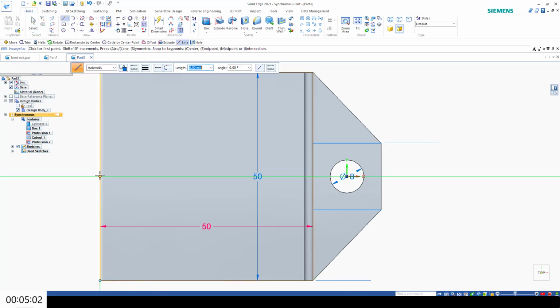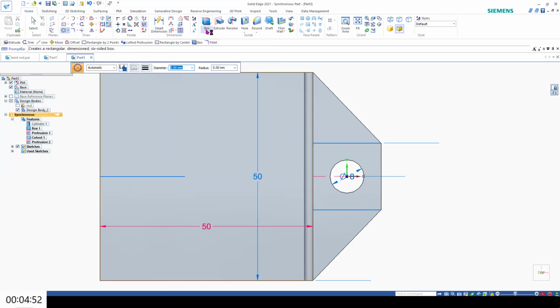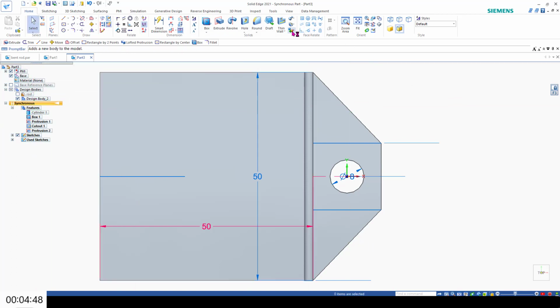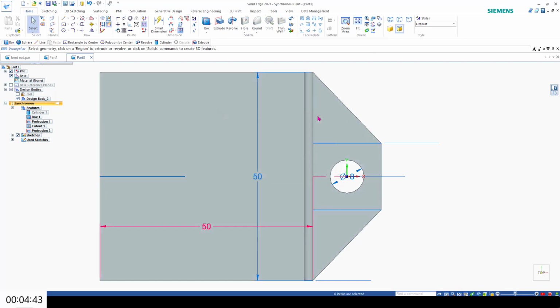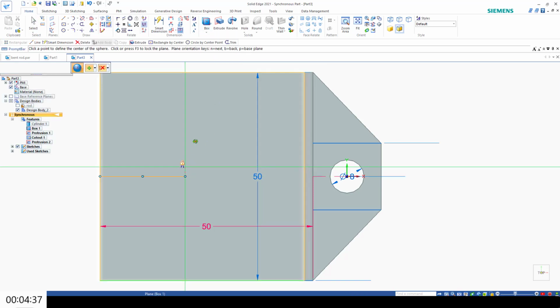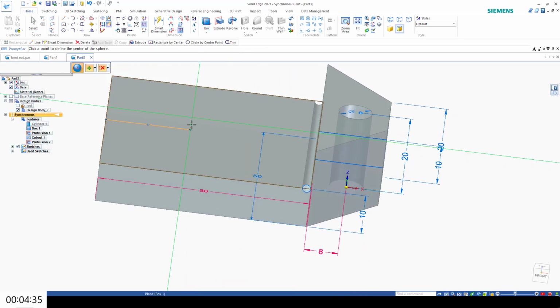Now the next piece I want to put in is I want to find the center-ish of this surface because I'm going to add in a bunch of dots. I want it to be rough. I want it to grip into an object. In fact, when I 3D printed this object, it was really, really rough, so I've been very successful at this. What I'm going to do is put a whole bunch of little tiny spheres on the surface and make a pattern out of them.